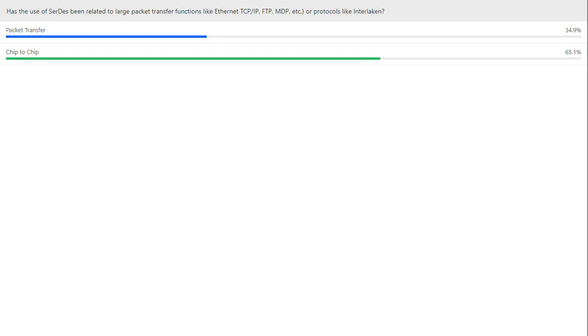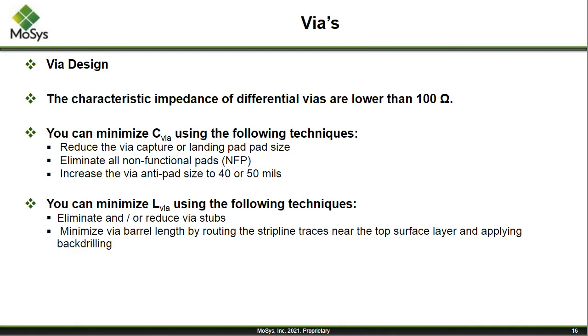We developed, as I believe Gus pointed out, a GCI protocol, and we did that because with chip-to-chip, you're certainly not going to suffer as severe an environment as you would going across a backplane and transferring large packets. So we developed a protocol that's very lightweight, but still gives you the security of a retransmit, being able to resend the signal if you have any issues with it. So it's been unusual to have people treat the chip-to-chip protocol as a higher priority than a backplane or an Ethernet kind of thing. That's great.